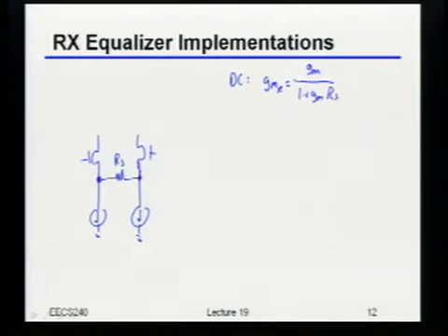Okay, now we just have to be a little bit careful. Notice how I tied this source resistor up. It's tied differentially across those two inputs. There we go. So it's RS over 2. Because remember, Miller effect, it's not just capacitors. If you double the voltage across a resistor, you get twice as much current, half the impedance. So it actually would be GM over 1 plus GM RS divided by 2. So if my GM was large, my effective GM would roughly be 2 over RS.